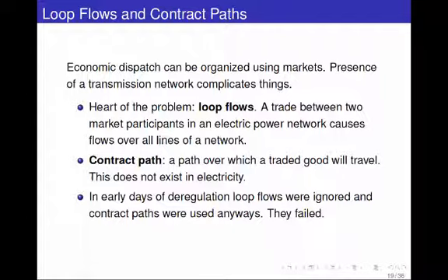It's the same problem that's going on now with renewable energy injection in Germany that is screwing over the Polish operator. Because all of the power fluctuations that are going on in the control room in Germany, some of them are entering the Polish control area, and they're basically screwing up the balancing of another country. This effect as a physical phenomenon is called loop flows. It's a result of Kirchhoff's laws, as we saw.